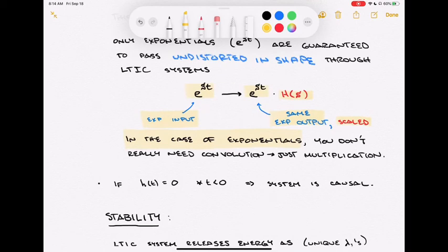In fact, as we'll find out when we get to chapter 4 and we formally talk about the Laplace transform, this is one of the powers of transform domain analysis. It can turn difficult operations in the time domain, such as convolution, into much simpler operations in the transform domain. Convolution, for example, becomes multiplication. Differential equations, which are hard to solve in the time domain, become algebraic equations. So there really is some interest in being able to look forward to this idea of doing transform domain analysis.